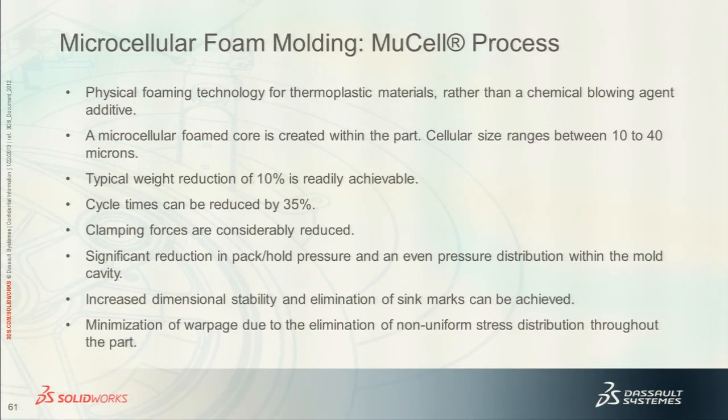One new molding process that I have gotten quite interested in, and I've only been able to do 2 jobs with it so far in the last 3-4 years. It's called microcellular foam molding or mucel molding. It's similar to structural foam, if you know what that is, where the interior material of your solid plastic part is cellular in nature rather than a solid homogeneous cross-section. And there are several different advantages of going to the mucel molding.